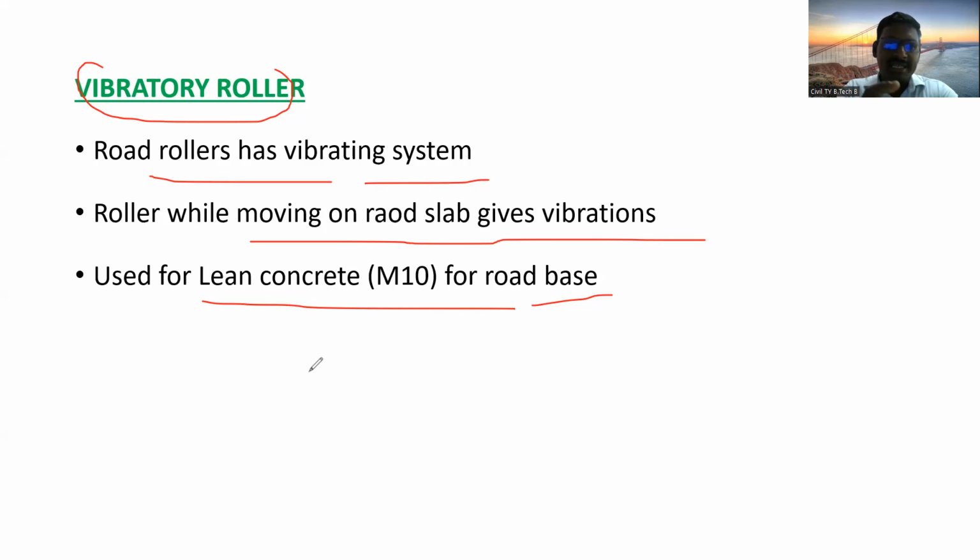But before that, lean concrete is there. Before that, lean concrete is there. That is the base for the 30 to 40 mm depth topmost layer of the concrete. The top 40 mm layer is M40 grade concrete, and its base is M10. If you have seen the construction of this particular project, lean concrete is there.